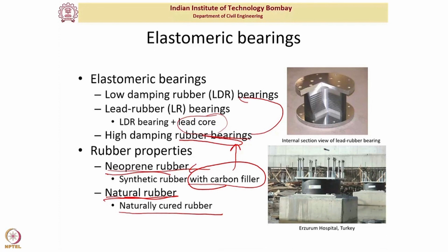That is why it is changing its property. Now, as a designer, if you are designing something that is changing its property over a long time, then you would prefer another type of material which has less change in property over time compared to neoprene, which has more change. So that is why for seismic isolation we are going with natural rubber now.